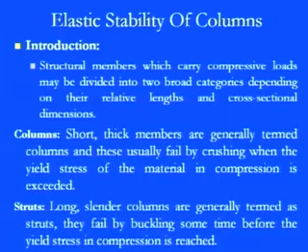This is a pretty sensitive part: when we are keeping a thin line between the column and the strut, we have to be very, very careful. If you take a length and it fails due to buckling prior to reaching the yield point sigma yp, obviously it is a strut. So this is the criterion through which we can say this is not a column, this is a strut, because it fails under the buckling load, irrespective of other things.